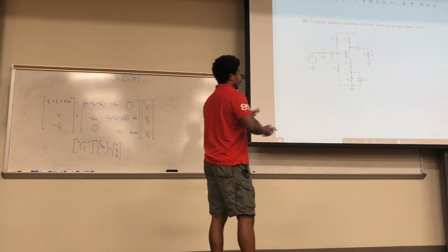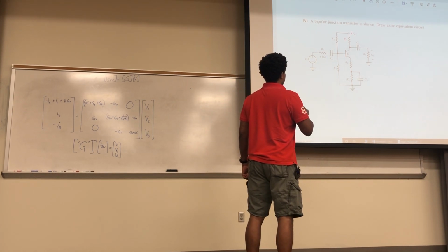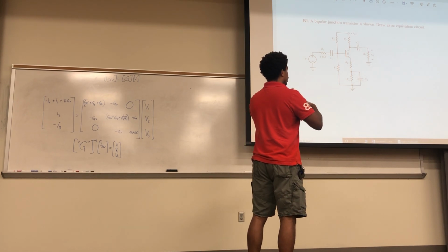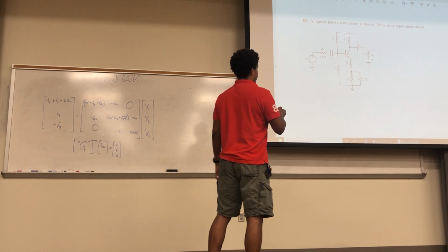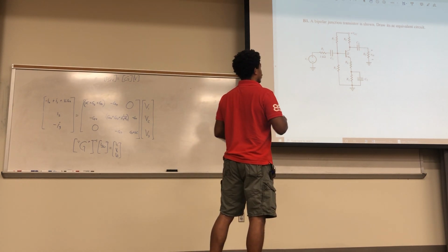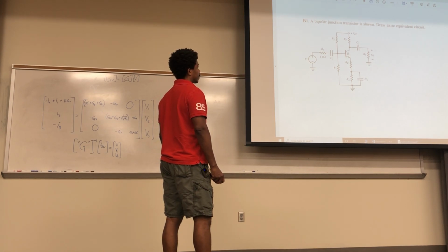If you want to change it around to say, well, if that's ground, and this is also ground down here, and you're starting at the same point voltage, then that R2 is going to be in parallel with that R1. If you want to change the circuit around to be like that, that's fine. If you're rushing and you just want to stick a ground symbol there, that'd be perfectly fine.